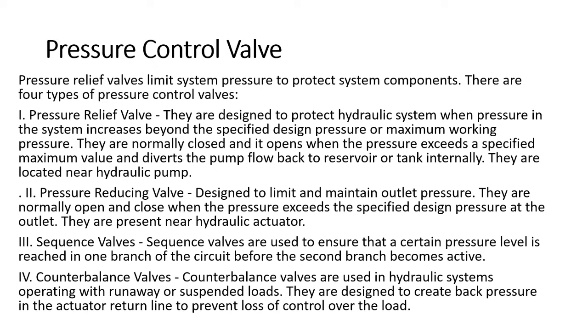Now, the next is pressure reducing valve. It is designed to limit and maintain outlet pressure. They are normally open and close when the pressure exceeds the specified design pressure at the outlet. They are present near the hydraulic actuator.